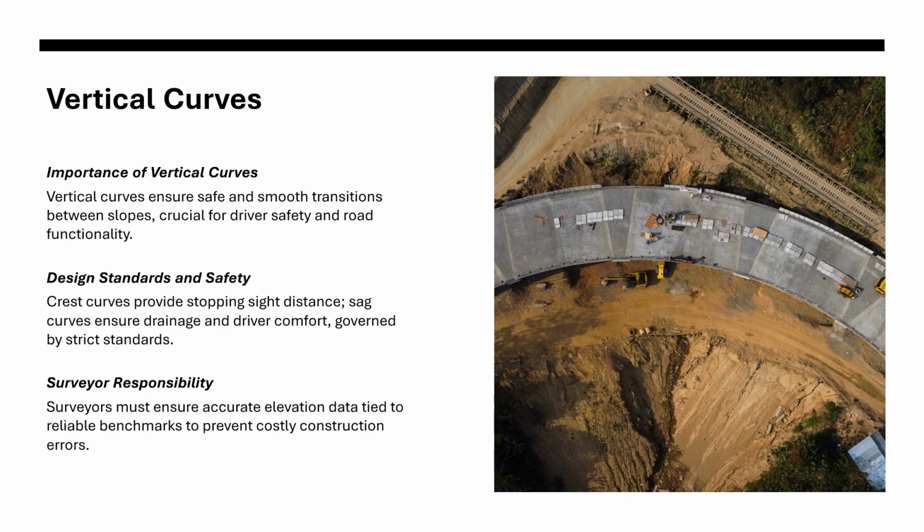They are governed by engineering practice, and in some cases by state and municipal codes. The surveyor and drafter, therefore, carry the responsibility of ensuring that the design profile meets these requirements. From a surveying standpoint, accuracy in profiles is directly tied to field data and control. Every elevation sampled for the ground profile must tie to a reliable benchmark.